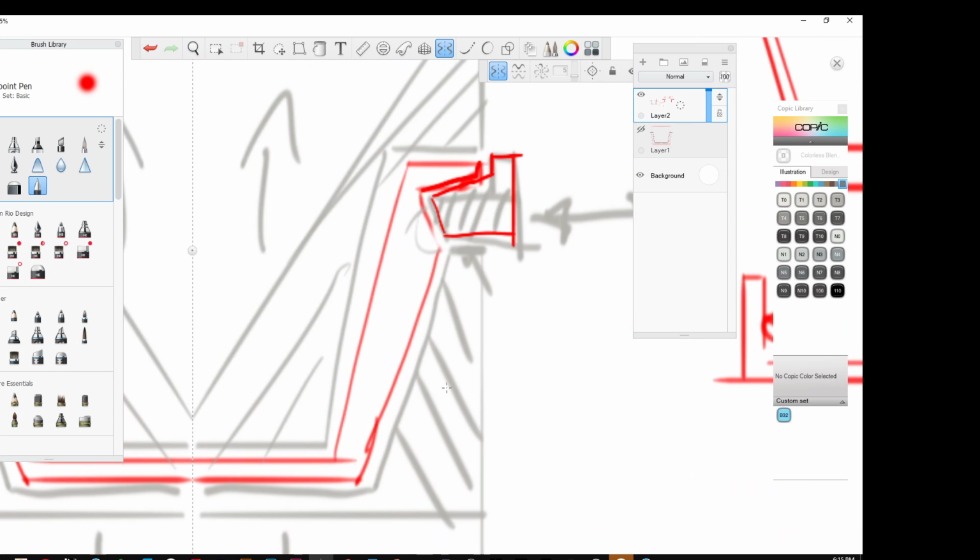Yes. So yeah, I'm guessing that the difference between that extra slide is manufacturing costs. Correct. Now, when I started my career, I always got told I couldn't do slides, I couldn't do lifters, because we manufactured in North America, and adding a slide would cost sometimes $20,000. Well, when we moved to China, that exact same slide, and this is why North American manufacturers lost out, Chinese manufacturers would say, yeah, we can do that, $2,000. So it really opened up the possibilities for what designers could do. But, again, can the product afford that?